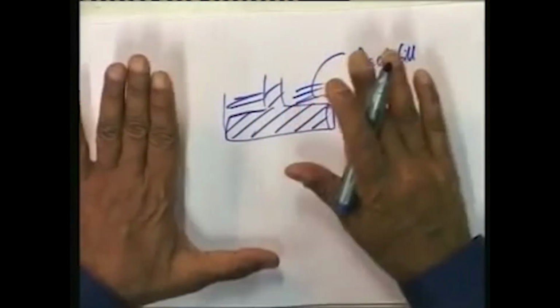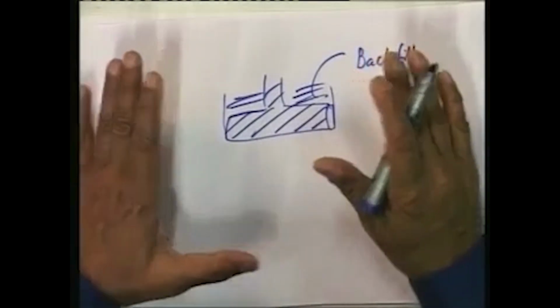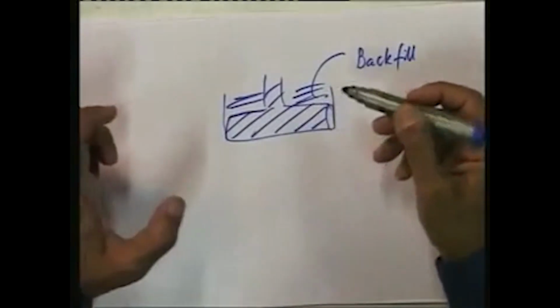Well, it is possible to take this into cognizance, but however, for illustration of the computation, I shall be ignoring the increase in stress that is arising due to concrete. I shall take the stress as purely that due to the soil, but however, the increase in stress due to replacement of soil by concrete can be very easily taken into account in the same procedure.